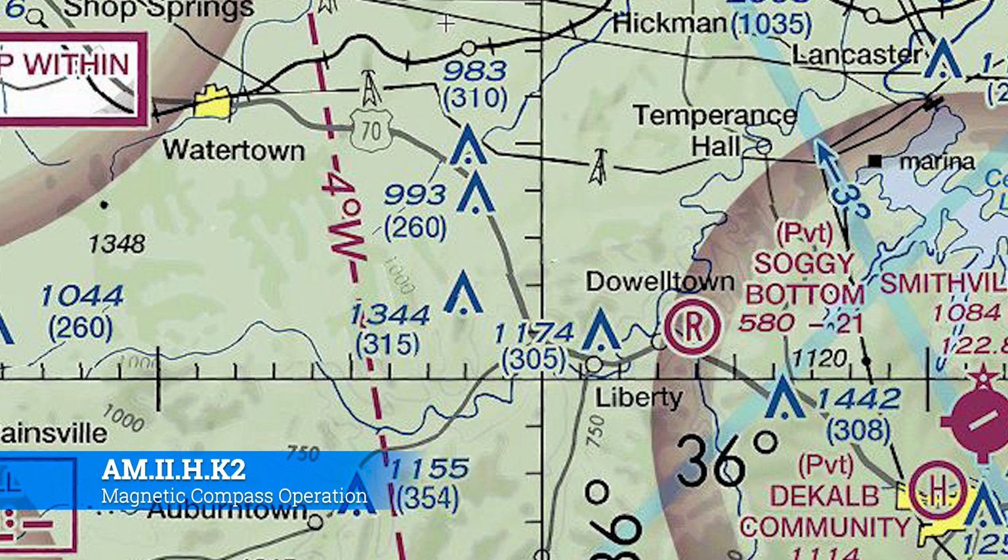There's an old saying that east is least and west is best. It means that if you're on a western isogonic line, you add it. If you're on an eastern isogonic line, you have to take it away. Now, you guys that have been in the military are probably very familiar with this, because land nav, you do the same thing. You'll look on your map, and you'll turn around and say, hey, look, we want to go from point A to point B, but we have to add and do all of this math, and it's on the bottom of every single military map to help you, so that way you don't get confused or lost. But that's variation.